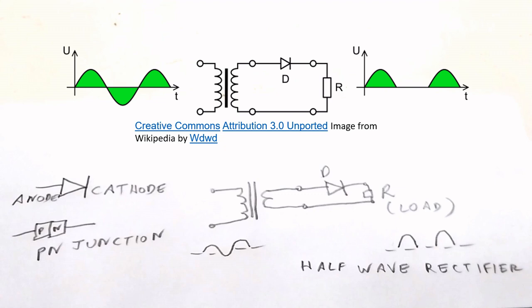Pulsating direct current output of the half-wave rectifier needs more filtering or smoothing network to produce a steady direct current output, as the waves are intermittent and at the frequency of the alternating current. Conversion ratio eta, sometimes called efficiency, of half-wave rectifier is about 40.5%. But a center tap transformer is not necessary for a half-wave rectifier.